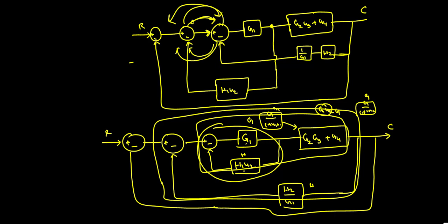But people have gone far more ahead and proposed a lot of other techniques to reduce the block diagram scheme. I'm going to discuss that in session number 7. Just by seeing the block diagram, how can we make a transfer function instead of doing so many block diagram reductions? That can be done with the help of Mason's gain formula, which is generally also equally correct as per this.